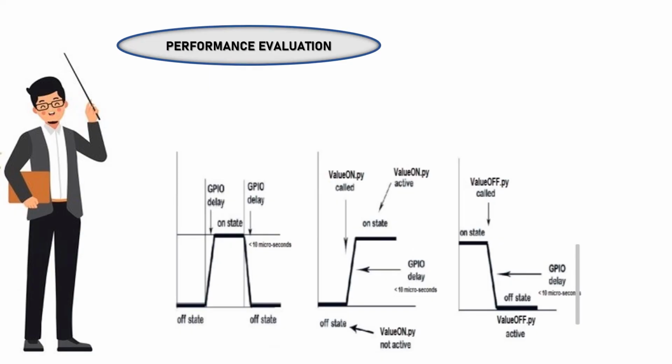The multimeter was attached to the RPI by connecting its positive node to the GPIO pin 26 and negative node to the RPI, where the user toggles the power button to turn it on. A PHP script fetches the data that the particular device is on, and stores it in a MySQL table. Respectively, it happens with the off button as well. In this way, we can see the hardware implementation using Raspberry Pi.